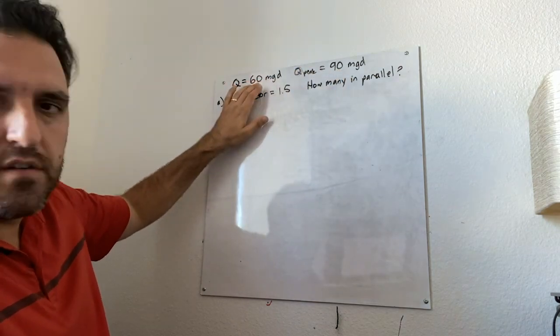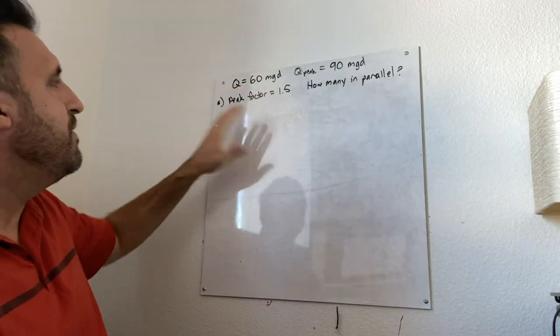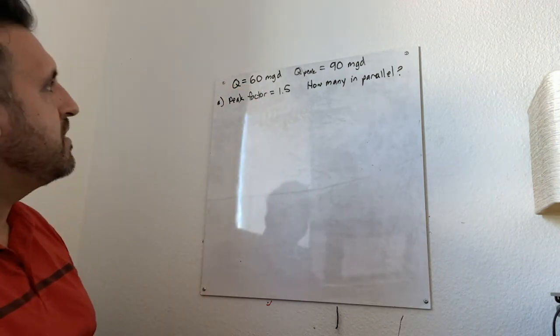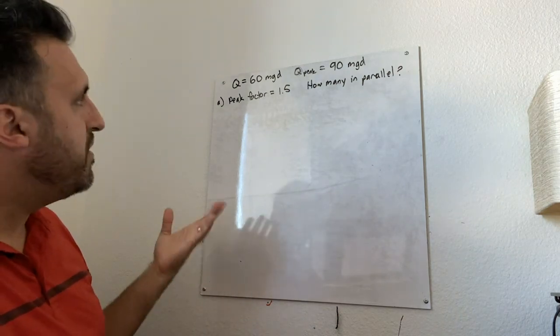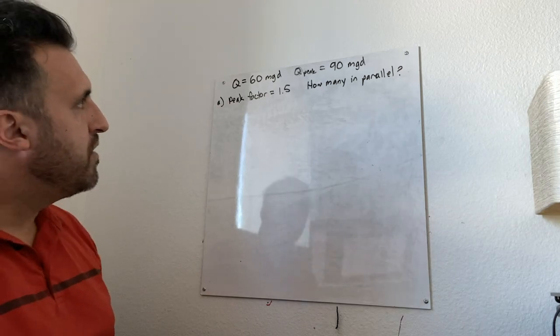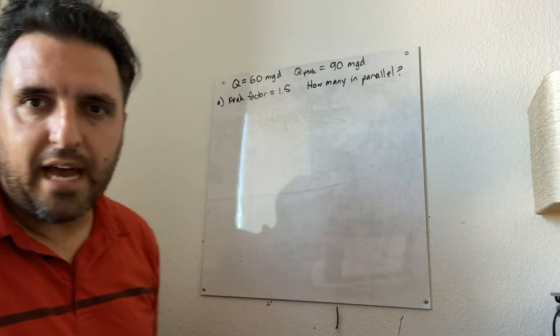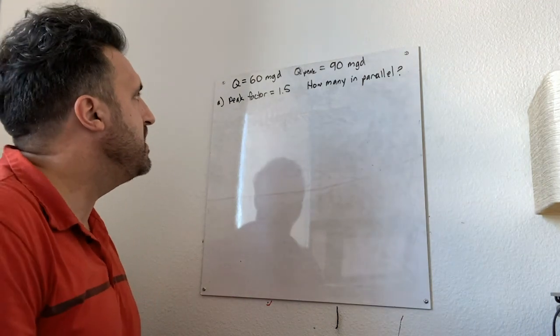When we're at average flow conditions, 60 million gallons per day, we've got 2 filters up and running. If we have lower flow conditions, like down to 30 million gallons per day, maybe we only have 1 filter up and running. So at the minimum, I would say 3. However, for a more robust system, you might want to double that to have 6. That gives you flexibility to use 5 at a time in case one of them needs to be offline.